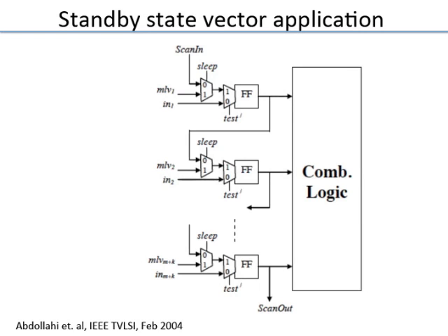So when I know that some piece of logic is going to a standby state, because you did clock gating, that whole block, the floating point unit, decided to shut off the clock because I'm not using it. When you shut off the clock to the flip flops, in the whole combinational logic there is no activity, because the clock is not there and all the data elements are fixed to some value. But what value should they be fixed to?